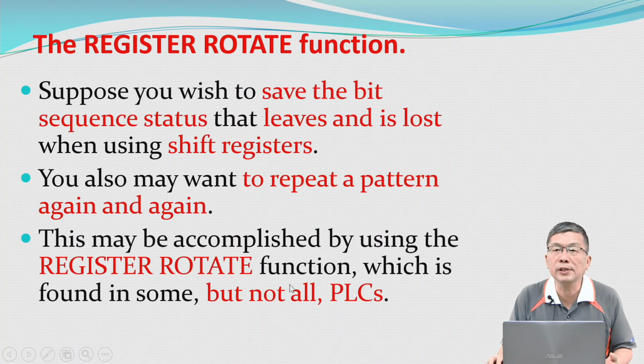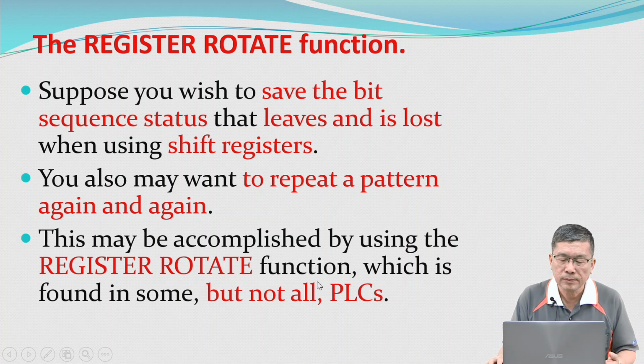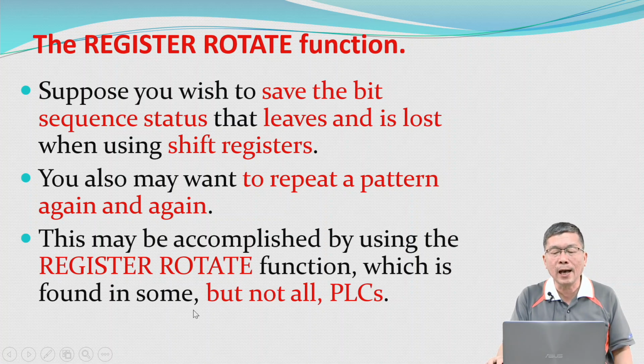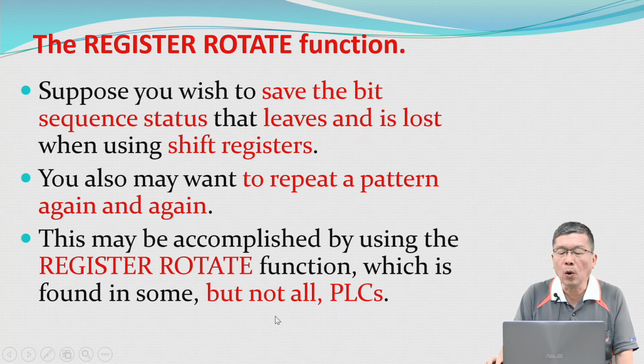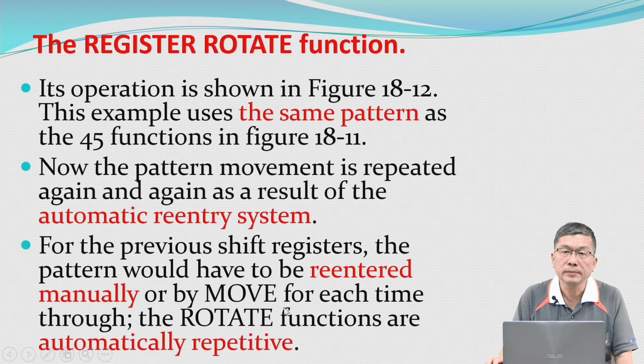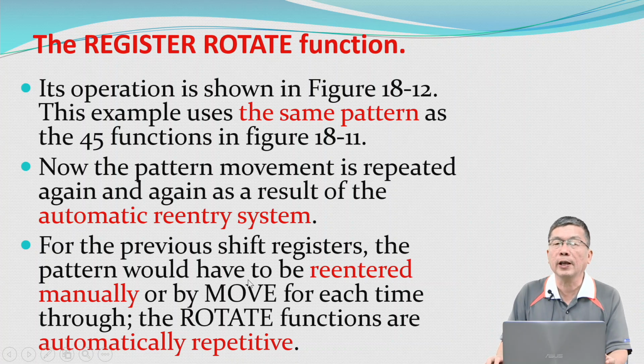Suppose you wish to save the bit sequence status that leaves and is lost when using shift register. You also may want to repeat a pattern again and again. This may be accomplished by using the register rotate function, which is found in some but not all PLCs. Its operation is shown in figure 18.12.